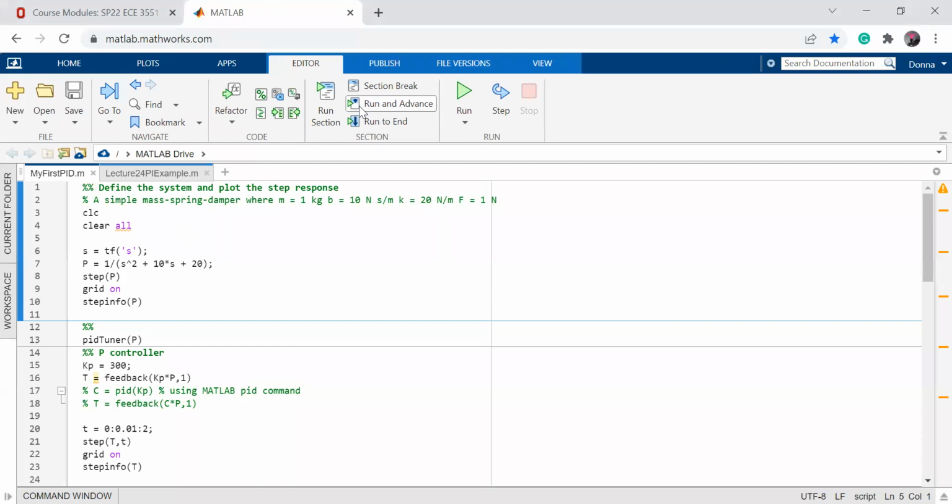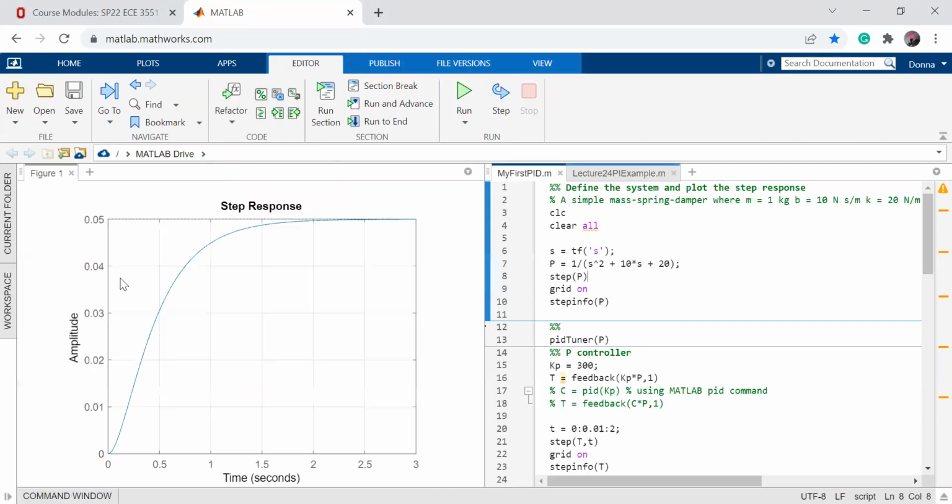All right. So this is from the previous code. I'm going to run it. If you remember, we had the transfer function. I'm going to show you the step function, and then we're going to see it in the toolbox. It's the same thing. So the step function in the toolbox, you'll see it with the controller. So this was our step function. We didn't like it. What did we want to do? We wanted to use a PI controller, right? To get rid of the steady state error and make sure that we get to the final output, which we were tracking, a step, right? So we wanted to get to 1. Do you remember this from Monday?